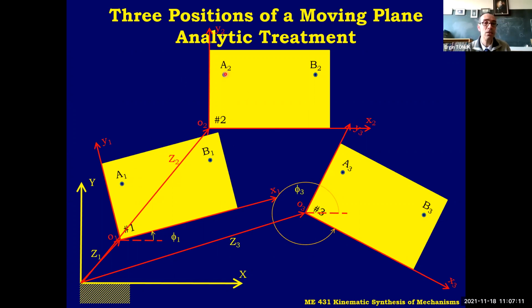You have these 3 points which define a circle uniquely, so its center is fixed. If you select this point, it again defines a circle that passes through these points. Its center is definite. You can directly design the 4-bar. However, you should check if all 3 positions are in the same branch, the transmission angle, link lengths, and so on. That's the visible part of it.